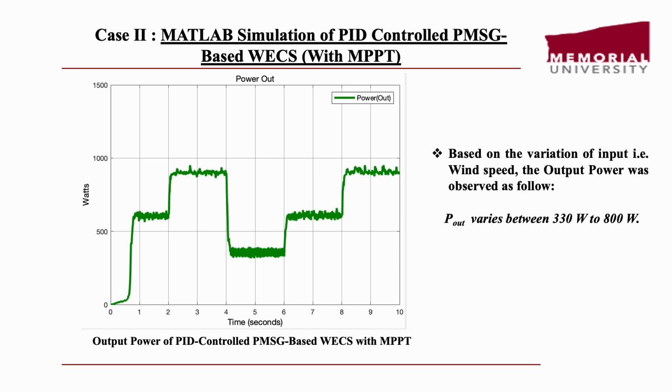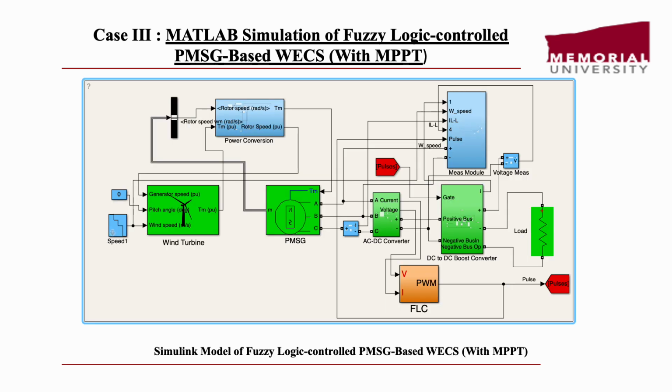Now we come to our final part, that is the simulation which is based on fuzzy logic control with MPPT. Here we can see that instead of the PI controller, we have implemented a fuzzy logic controller, and it provides a pulse width modulation signal as a pulse to the same gate of the DC to DC boost converter.